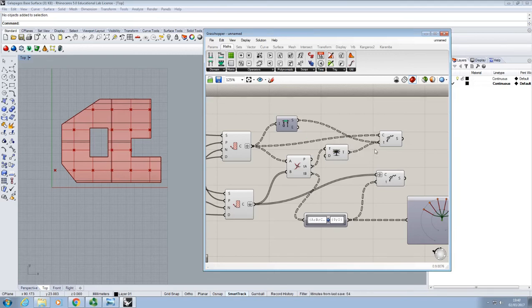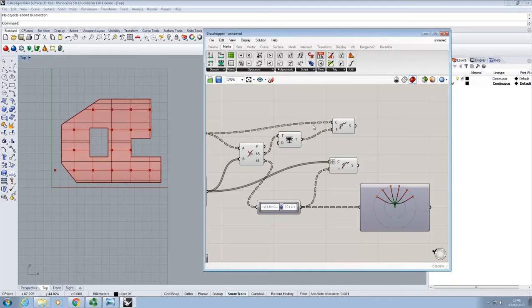That will make sure that each curve has its own intersection point, and you will actually get an output. So it'll try and cut it at the start, and you'll just get out the complete curve again, because if it cuts it at the start, then it will just give you the whole thing. But it's just a way of ensuring that you get all of those bits out. It looks like in this case it's not actually necessary, so I won't complicate things unnecessarily, but if you ever come across that problem using this Shatter component, that's one way of getting around it.